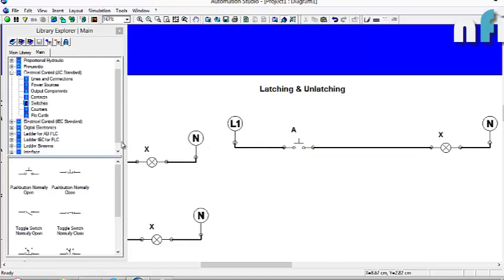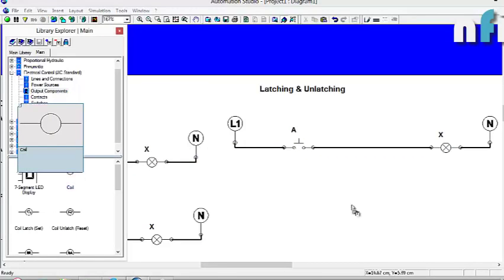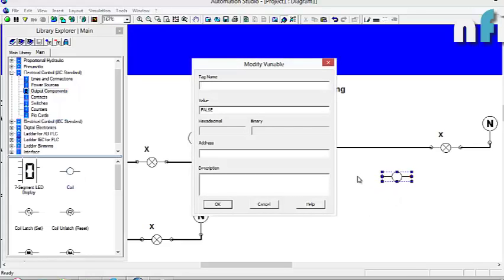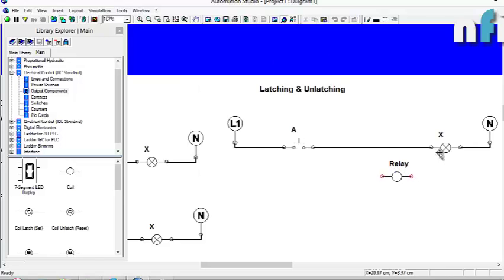To make that we need an additional component called a relay. A relay is an electromechanical switch in which we have a coil, this is a coil, and we have some contacts. Let me tell you what this coil and contact are. A coil is basically a wire wound in a round shape. If you provide a signal to this coil, it will become an electromagnet. It will start having a magnetic action, and due to that magnetic action, it will attract and repel a contact.